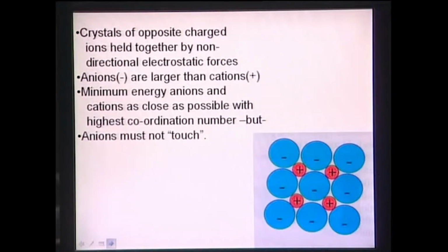Now, here in this view graph, you can see this particular ceramic, let us say X ceramic, has largely ionic bonding. Ionic bonding means these are positive cations and these are negative anions, which are ionically bonded to each other. The rule of the game is that anions must not touch each other.